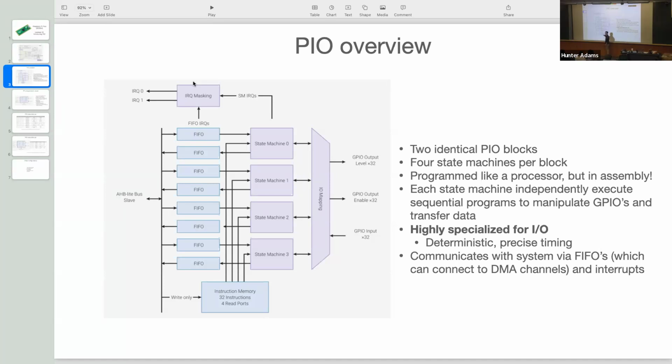It's an awesome constraint. Okay, so these end up looking like little poems, right? There's very few lines there, and so they're simple programs in that they're short, right? But with very few lines, as we'll see, you can generate a ton of complexity. And so it's an awesome exercise in very, very constrained engineering. You only get this many lines of code. So given some goal protocol that you want to achieve, VGA or CAN or LEDs or whatever it may be, you have to achieve whatever you're trying to achieve in less than 32 lines of code per PIO block.